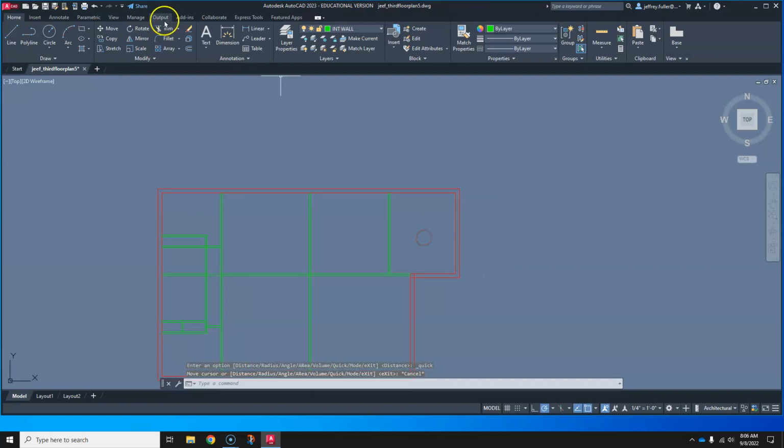So that's still good. So let's grab the line tool. And we're going to come here. We're going to hover to turn on that point right there. And then we're going to come down, and I'm going to put in there 5 feet. Type 5 feet, hit enter, and of course that line starts at that 5-foot point. Drag it over here, do an offset. Still says 4.5 inches in our dynamic input. Hit the enter button, and then offset.